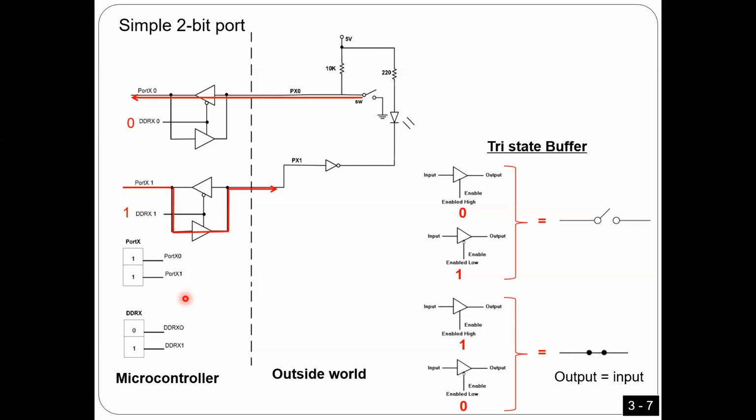That means if I want to put 000 here, all you have to do is say, for example, move byte, and then you put here, for example, number 0, comma, and then you have to put the address of port B, for example, the address of the data direction register for port B. Yes, you have to do it this way. Is that okay?